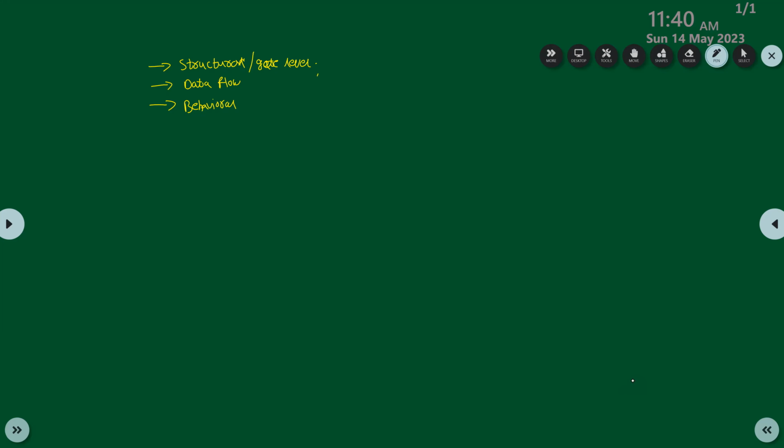Okay, I'll cover it up. But before that, you need to understand one important keyword, assign. That example I'll cover. I'll take one truth table and write the expression. I'll try to define it with structural, behavioral, and data flow, all the ways. So first you need to understand the assign statement, and the need of it.